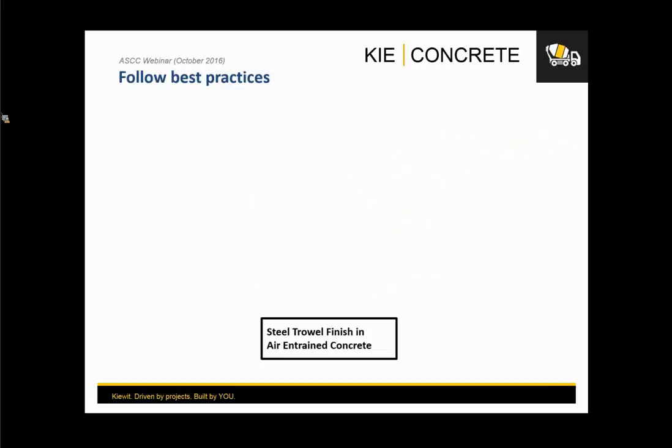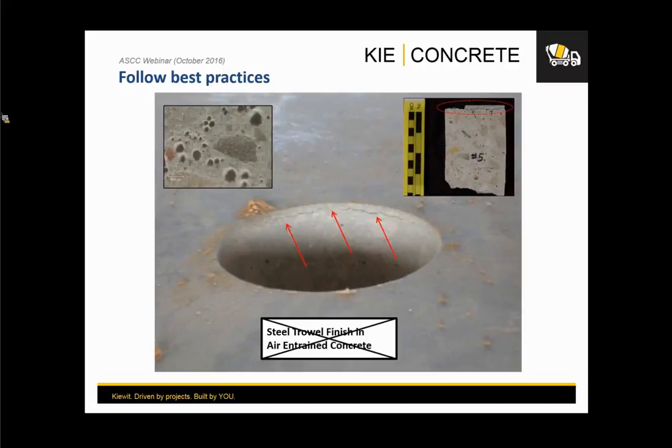What about best practices? That one is kind of easy for many of you in concrete construction in buildings, right? Steel trowel finish in air-entrained concrete. What is that? That's a no-no. Steel trowel finish in air-entrained concrete, that's a no-no, right? So obviously, things happen.